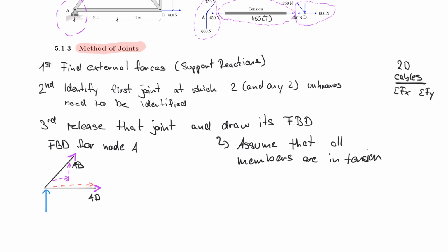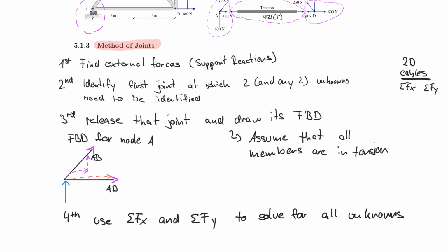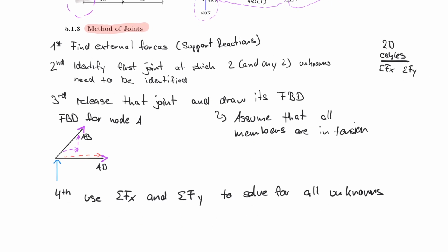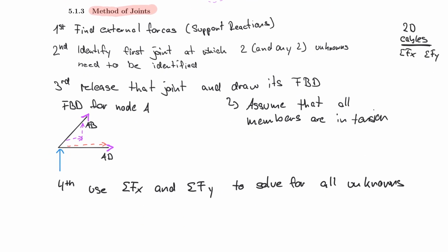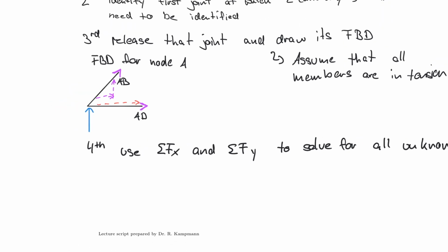So my fourth step is use sum of the forces in X and sum of the forces in Y to solve for all unknowns. And we can do that, like, again, this is only conceptually here, but I'm not going to solve it here. We'll do that in an actual problem in the next slide.